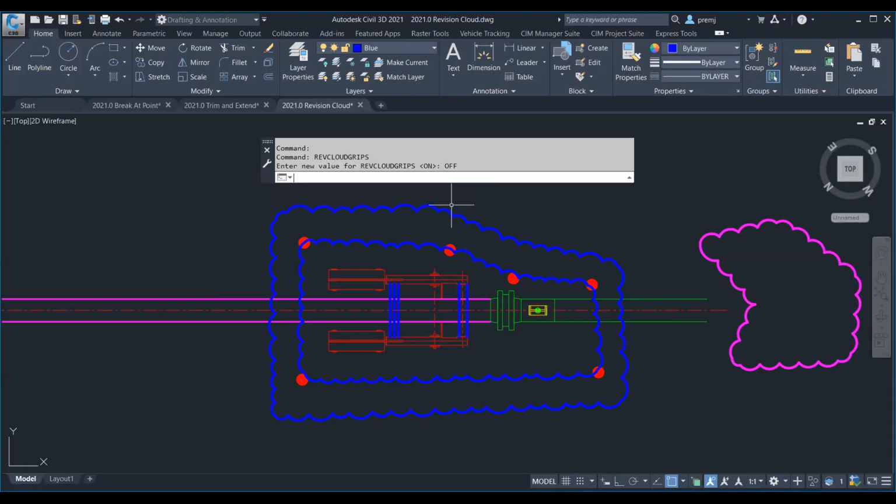When turned off and you select the object, it's more like the polyline grips. For every arc, you're going to see endpoints and the midpoint. Okay. The off and on situations. And the on situation is going to be specific to the new type of entity, the Rev Cloud grips. In other words, the original segment is treated as one set of objects, one object, not each arc.